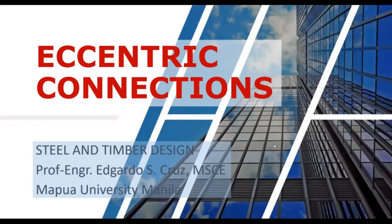Okay, so kailan ba nagiging eccentric ang isang connection? Kasi yung previous discussion natin is simple connection. So dati, 'di ba, when we say simple connections, the load applied in the connection passes through the centroid of the group of bolts, rivets, or group of even welds. Kapag yung load passes through the centroid of the connections, that is considered as simple connection. When we say simple connections, direct shear lang siya.